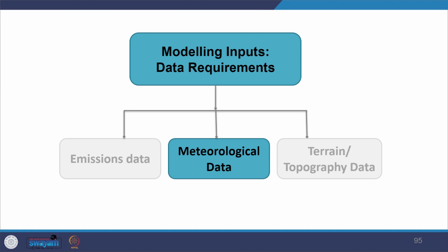You have to use the data as per the location and the assessment you are making. So where the assessment is to be done and to what detail do you need it. It is suggested that as weather patterns vary from year to year, when modeling is undertaken for large scale industries installation, one should use 3 or 5 years of meteorological data and should compare the results. Even CPCB gives you these guidelines, you may look into that.